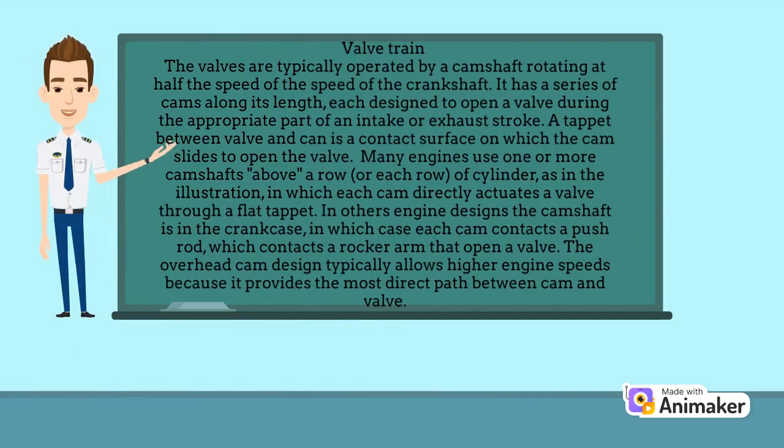It has a series of cams along its length, each designed to open a valve during the appropriate part of an intake or exhaust stroke. A tappet between valve and cam is a contact surface on which the cam slides to open the valve. Many engines use one or more camshafts above a row or each row of cylinders, as in the illustration, in which each cam directly actuates a valve through a flat tappet.